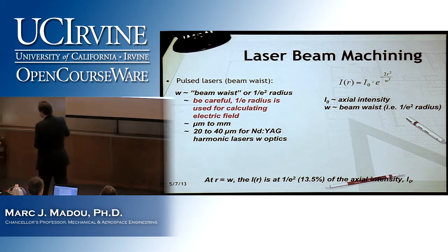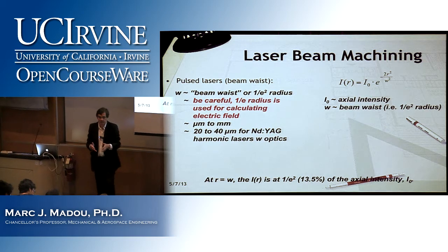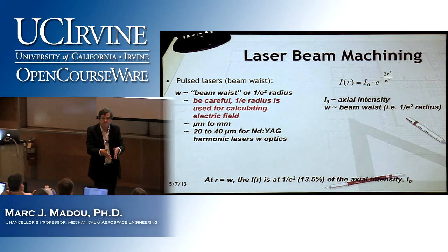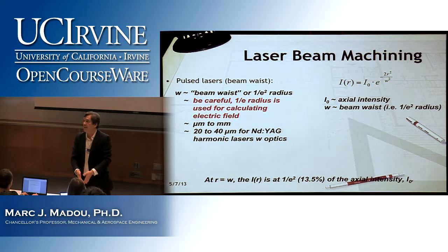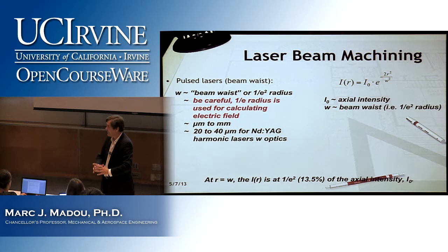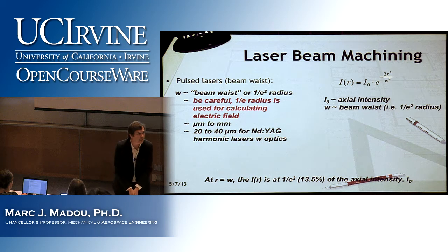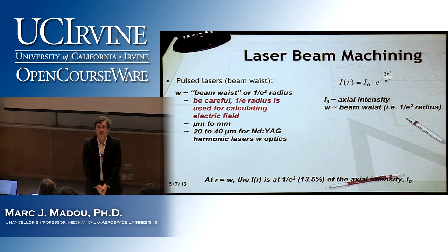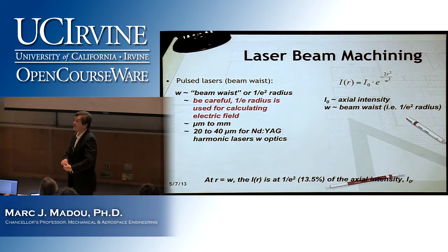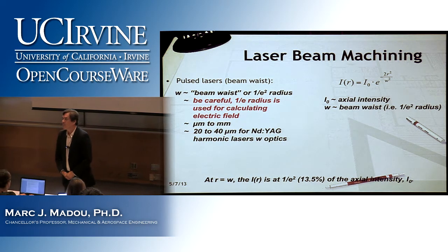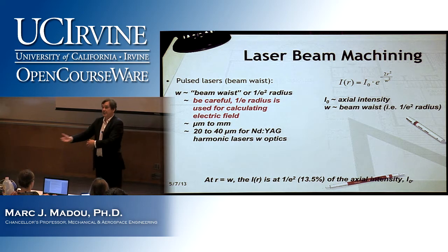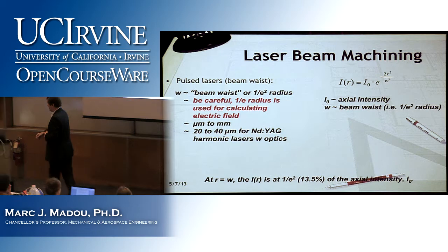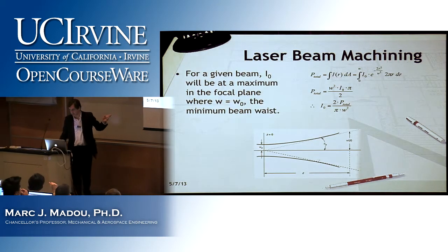And so what we are doing here is basically calculating how small a laser beam spot I can make, depending on the wavelength and the lens that I'm using. And you can understand that's important, right? Because the smaller I can focus that spot, the better my machining will be. We also want to have a good depth of focus. Now, I will jump immediately to these equations. For graduates, I will expect you to read these slides here.